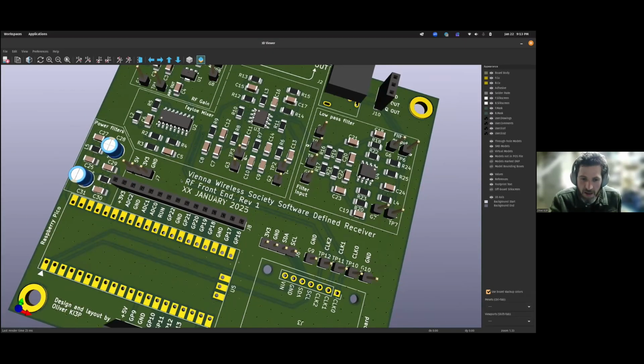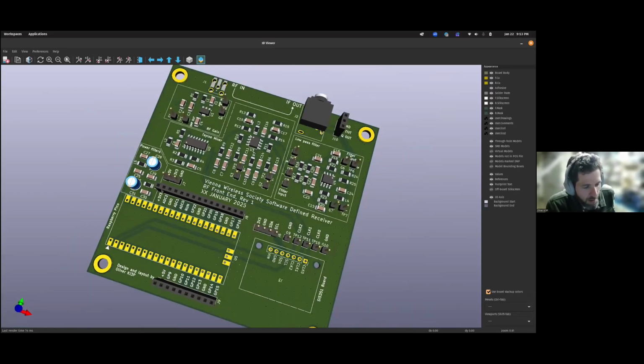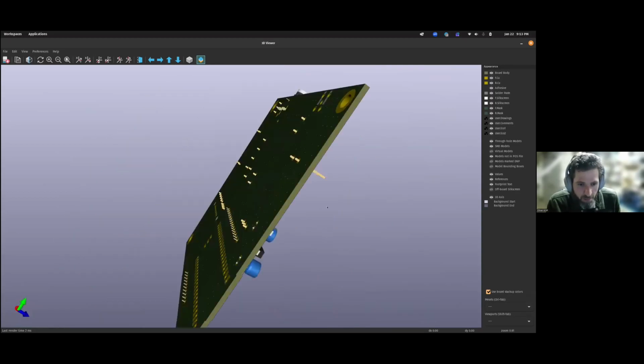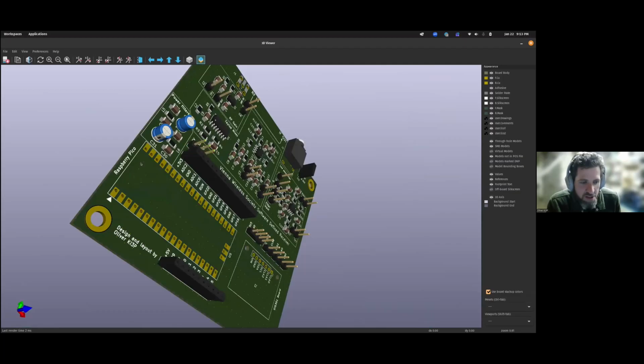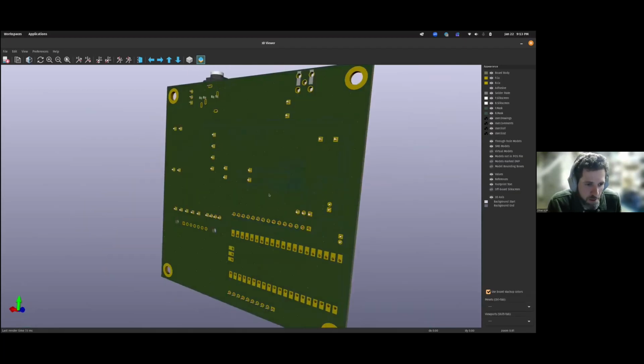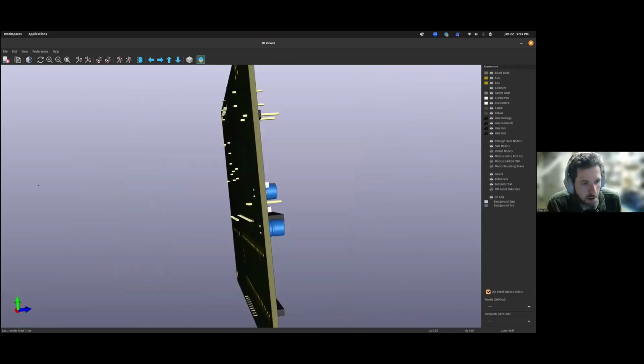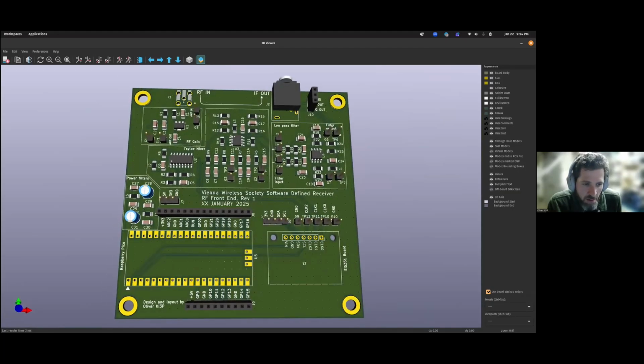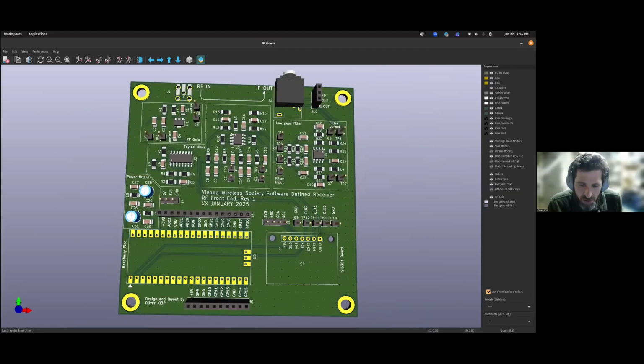So if you have many layers to play with in your PCB and you're doing this professionally, you can do things like that. But for the purposes of a rank amateur like me, I tend to keep my signal traces on the top to the greatest extent possible, keep my power traces on the bottom, but it's just a general principle. It's not a hard and fast rule.